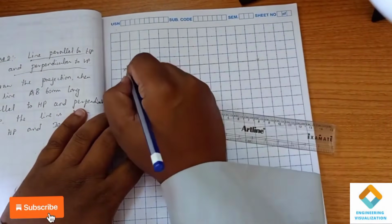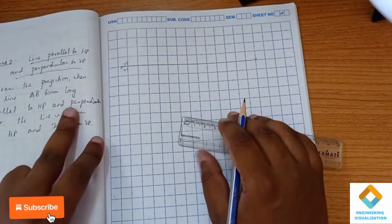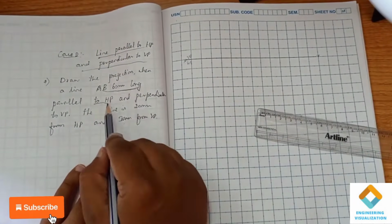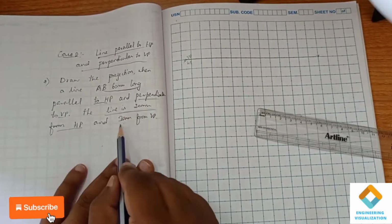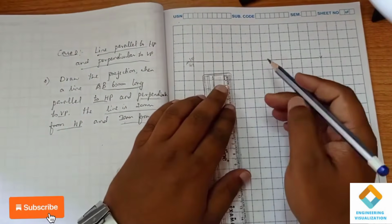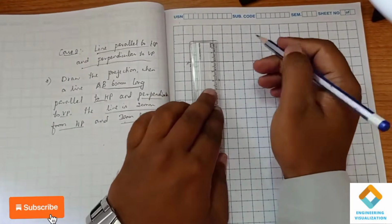XY, VP, HP, first quadrant we are using. Line AB has to be made parallel to HP and perpendicular to VP. The line is 20 mm from HP and 30 mm from VP. 20 mm above HP means it is in the front view.